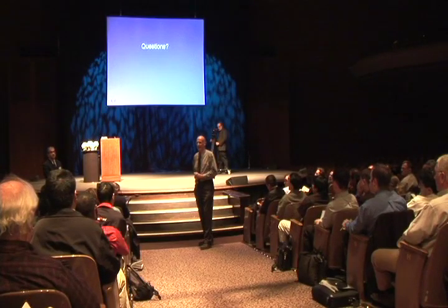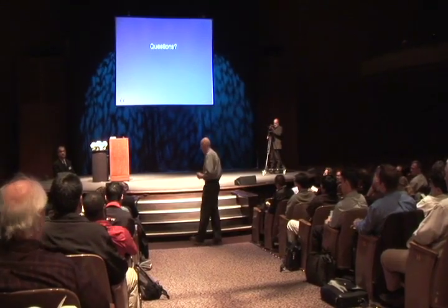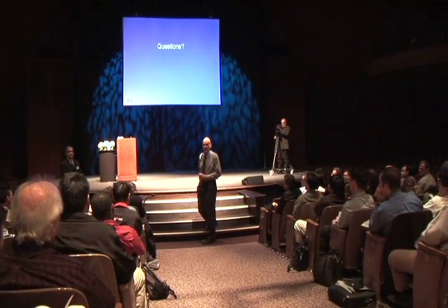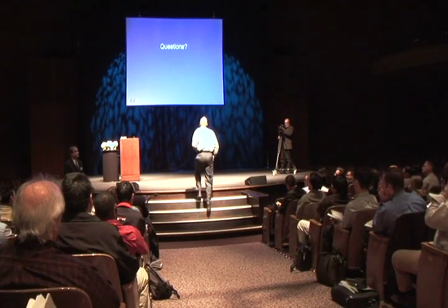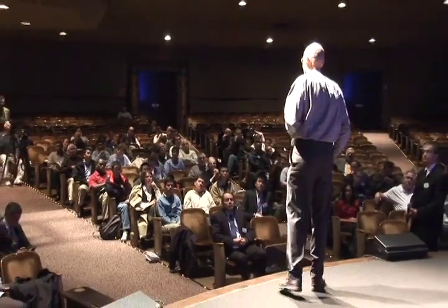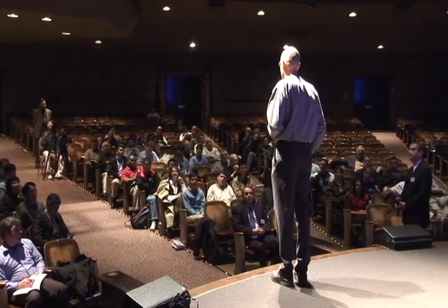Well, I could be wrong, but if you have a moment-resisting frame, not a braced frame, an unbraced frame, maybe with the shear wall moment frame kind of structure, or something more of a braced frame, either braced by a shear wall or otherwise, again, I'm not really sure they're going to buckle. I know you have L/R ratios and things for columns, but I'm not sure they ever really buckle. However, this gets into the class of problem that I indicated for braces. It was the very last slide that I showed.